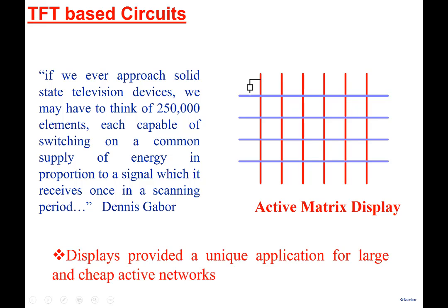So this was, as I said, the initial thought of the people who invented TFT, that if and when solid state displays are made, then because of large resolution, you would require the pixels to be arranged in the matrix form. And to selectively turn a particular pixel on or off, you would require a switch, meaning a transistor. The transistor will have to be fabricated on such a display made on glass, large area display made on glass, and therefore we would require a TFT. Okay, so that was the thinking at that particular time, why one would require a TFT.